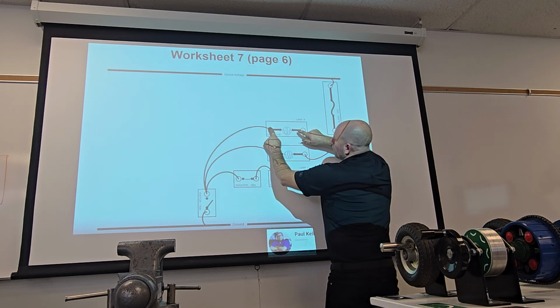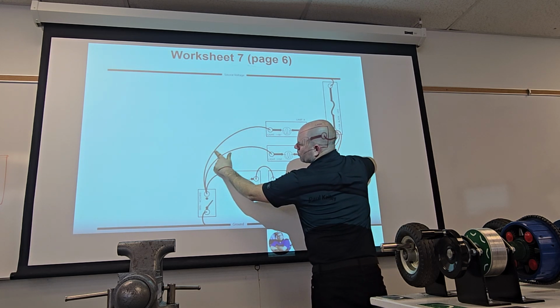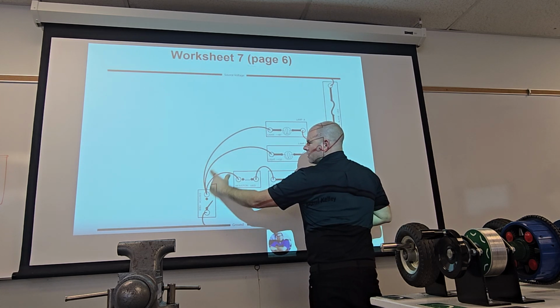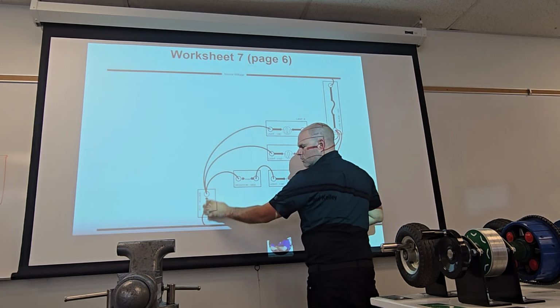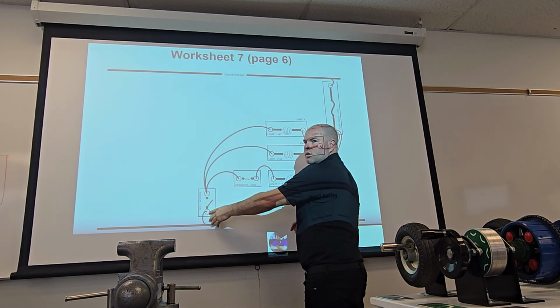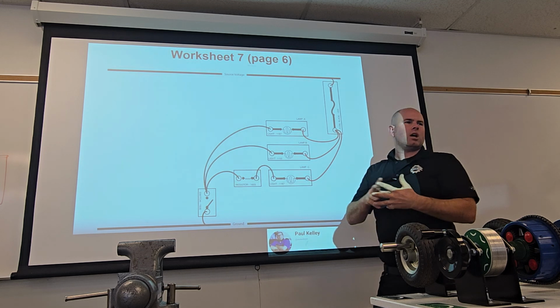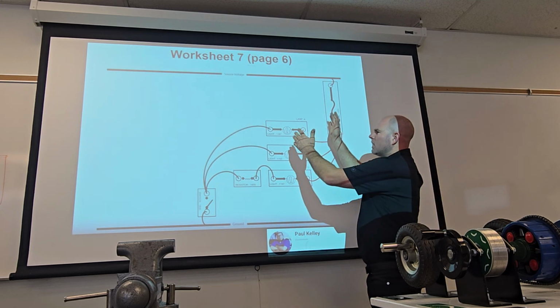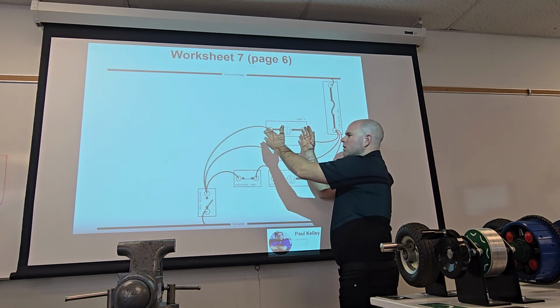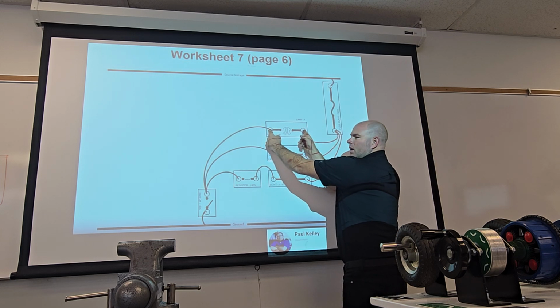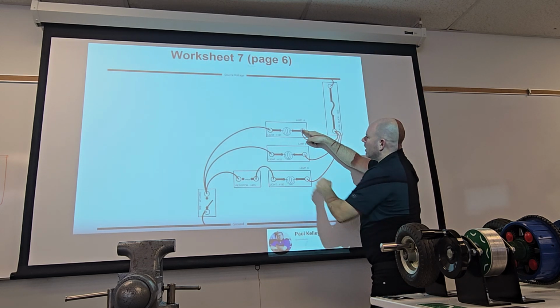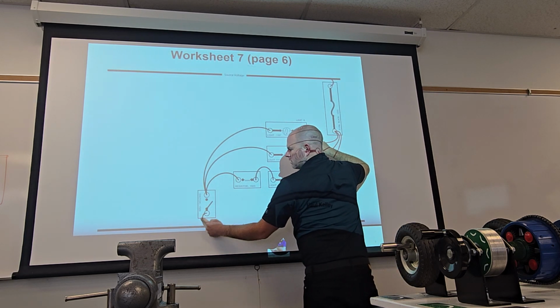If we get over to here and it's going through the wire, should we drop any voltage? Should we drop any voltage through a nice, good condition closed switch? But remember some of the laws of electricity, it should drop the entire source voltage in the circuit, so all that 12 should be dropped right here. It should go from 12 to 0, 0, 0, 0, 0, 0.